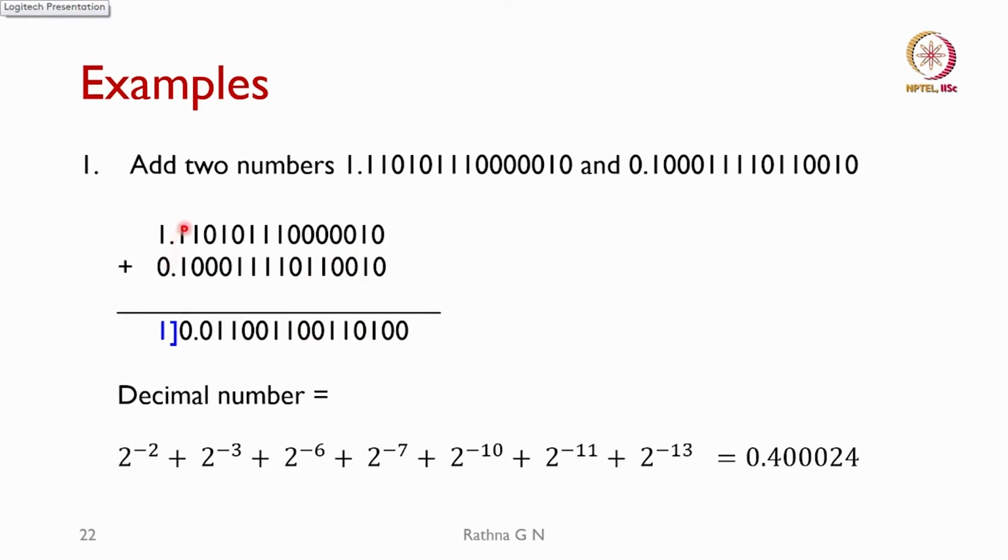When you come to the last one, you will see that 1 plus 1 is 0, and when I put 1 here, it will be 1 plus 1 equals 0, and then I will represent it as 1 0 here. Then, as shown in blue here, I will be discarding the number coming at the most significant place of the number.